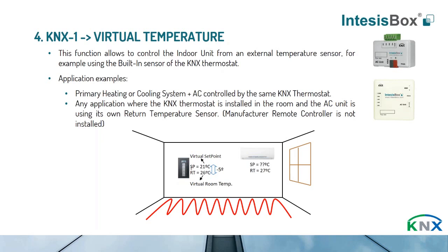Okay, thank you very much. So here, a very Intesis-specific question by George. Some new split units have Wi-Fi communication. How do we communicate using Intesis? We will not use this Wi-Fi communication. We will use the direct connection to the unit.